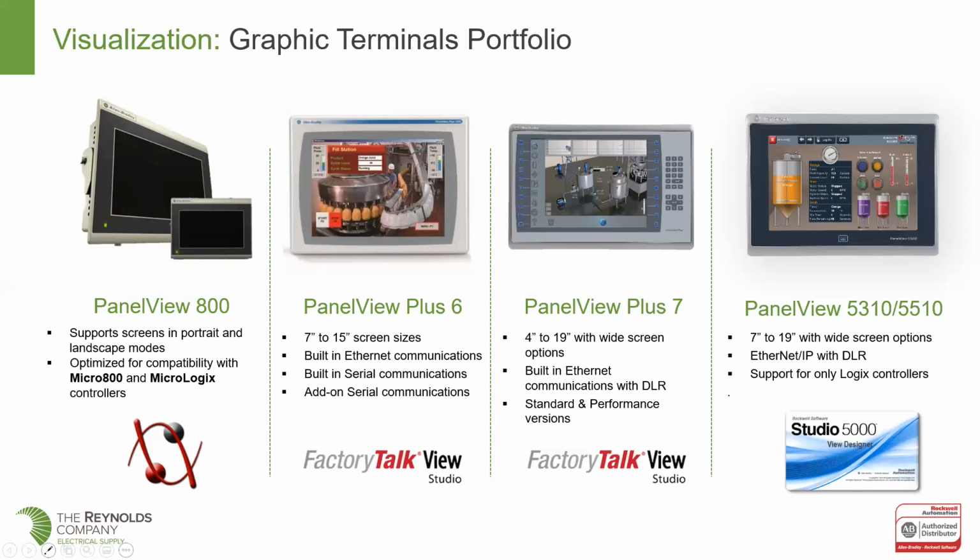And the really important thing to understand about the 5000 family is that it only communicates to Logix controllers. The 7s and the 6s can talk to other PLCs out there, not just a Rockwell controller. But the 5000 family is only Logix controllers, which means Compact and ControlLogix.